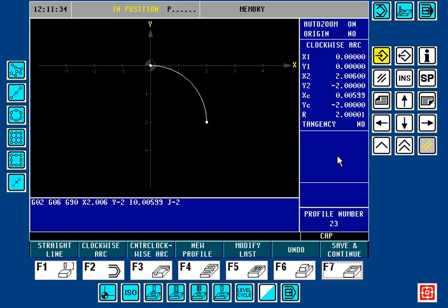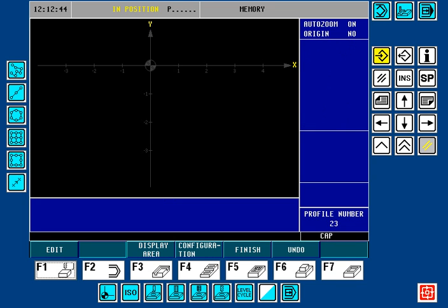A lot of times you're working from a blueprint and you're working from a 3-place decimal, and those values are rounded. And sometimes when entering rounded values, you'll run into a conflict. The profile editor in the Fagor can go up to a 5-place decimal. So you'll have to expect that sometimes you'll have to leave one or more values floating, which means that they're adjustable by the profile editor during the validate. Let's now look at a second example of error in profile data.